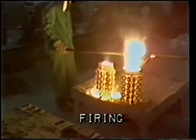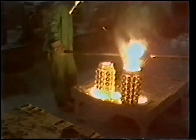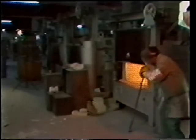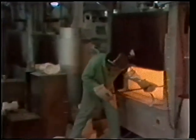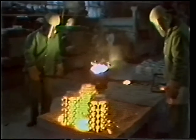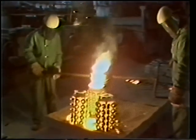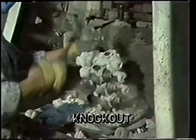Molten metal is then poured into the mold. The mold is preheated to assure that the metal will flow more readily to all thin sections. This procedure also gives better dimensional control because the mold and the metal shrink together during cooling. After the metal cools, the casting is removed from the mold. This is done by breaking the brittle mold away from the casting.